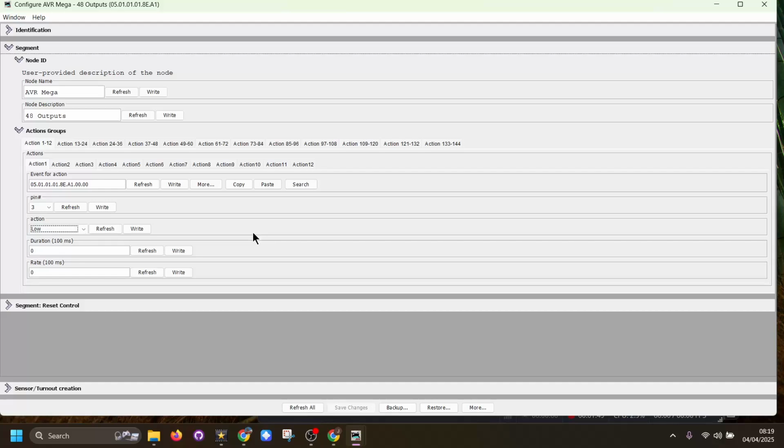And again, using the Arduino Mega is not that expensive. I am still testing this module using the MCP2515. This may eventually get looked at for a different CAN module, but at the moment I think this is going to work okay. So with these different nodes now made available to you, I think it's developing into a nice little system of nodes.